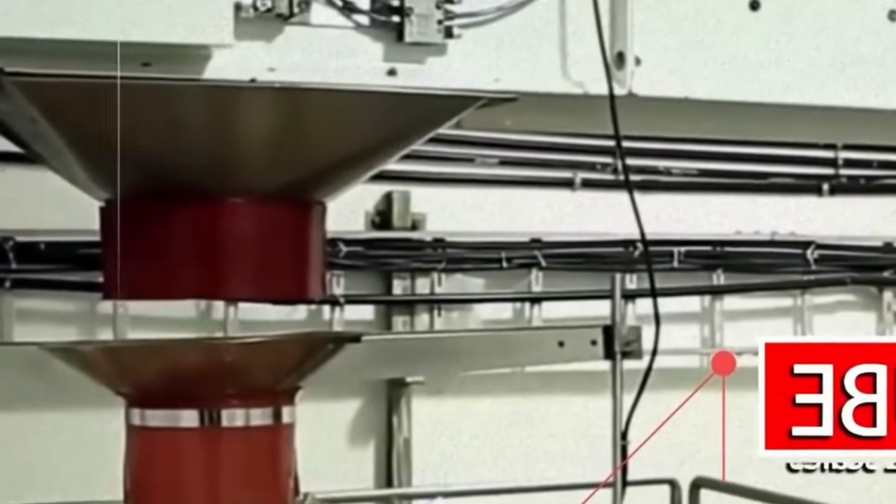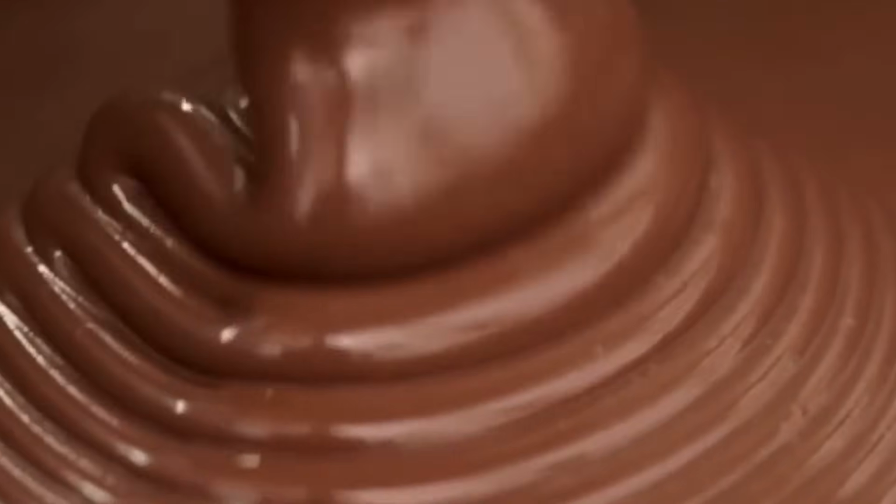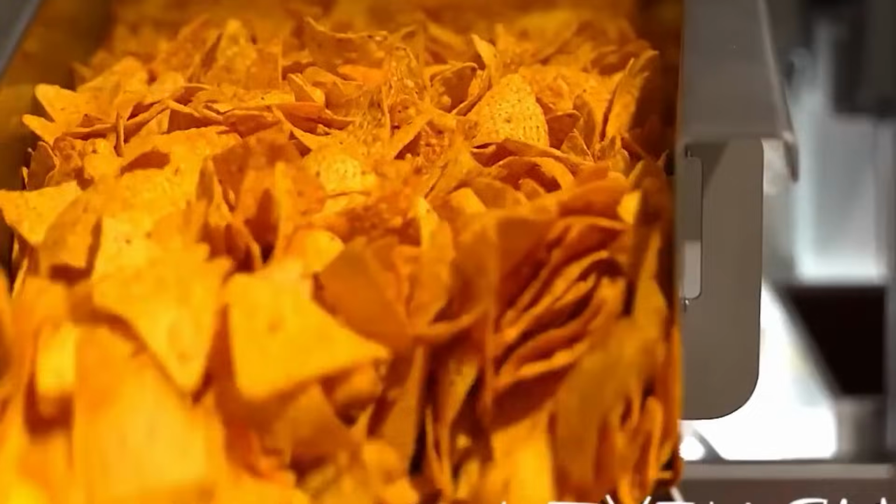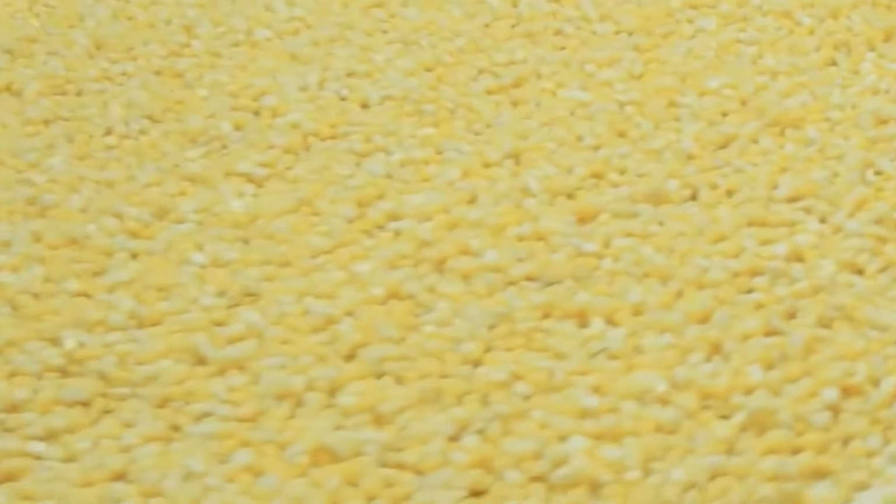The stone mill grinds the wet corn into masa, a soft, pliable dough. The grinding mechanism consists of two stones, one fixed and one rotating, with adjustable spacing to control grind texture. The heat and friction from grinding partially gelatinize the starch. The resulting masa is collected in a trough and transported via auger to the sheeting system. No preservatives or additives are introduced at this stage.